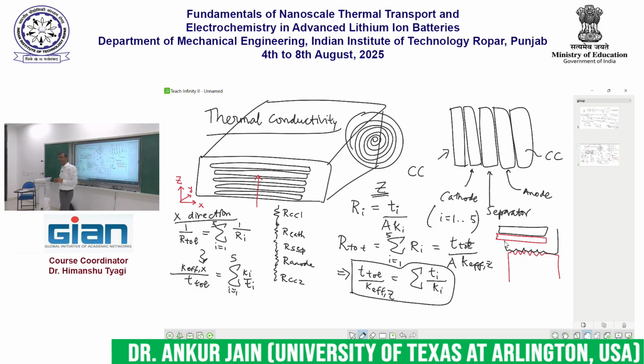Because of this imperfect surface contact, there is always a resistance to the flow of heat across this material. Imagine in the worst case, if these two materials are barely touching each other, then heat will not be able to flow across. In other words, the interface will offer a very large resistance to the flow of heat. If on the other hand these materials are very, very smooth and touch each other at 99.9% of the actual area, then heat will be able to flow very smoothly across the interface.